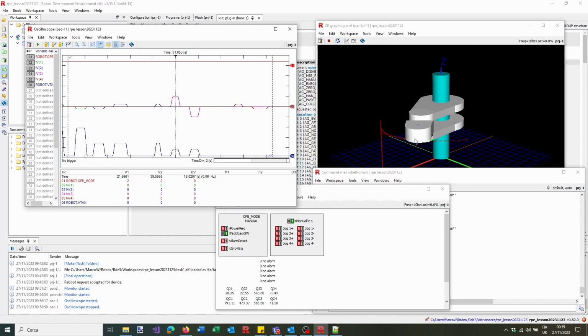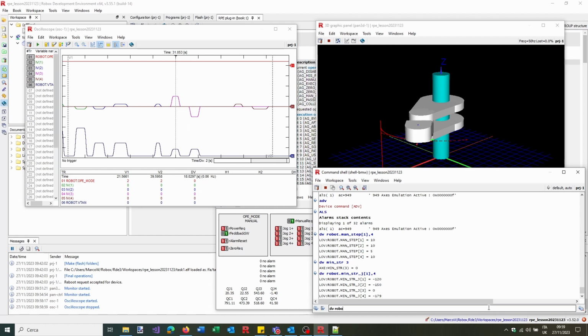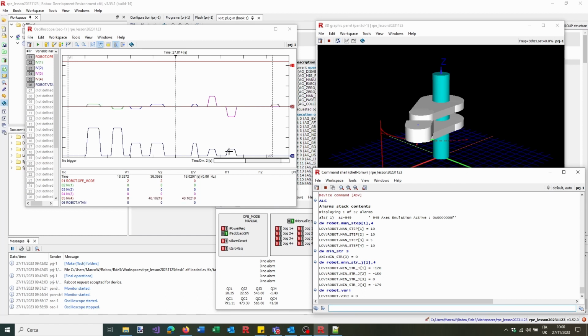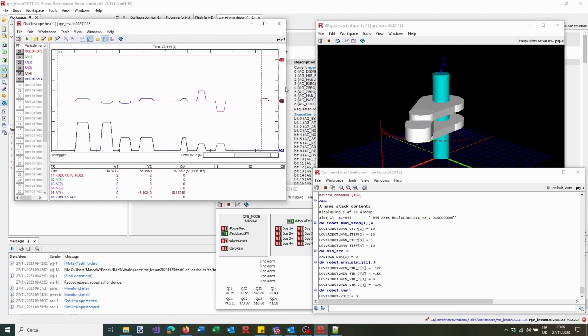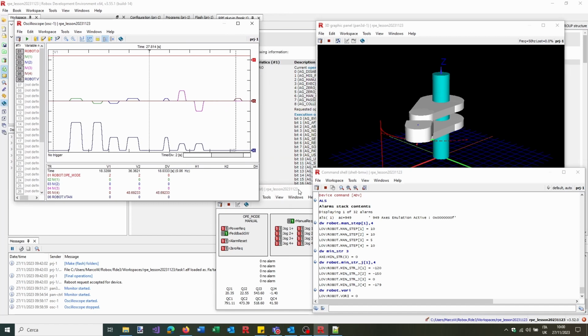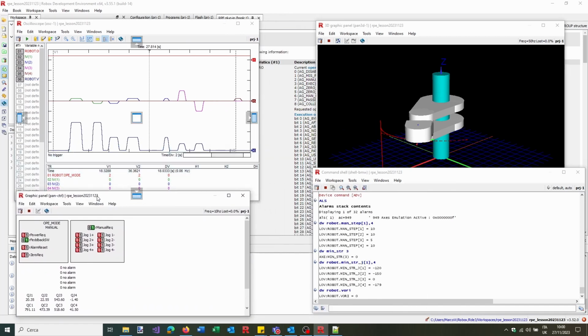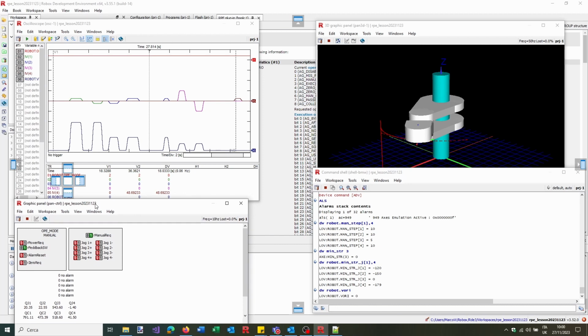It is only changing the orientation. So if you want to see it together with VTAN, you can also have V-ori like this. So this is the speed of the orientation path. Normally we check VTAN, which is the limiting one during all the motion. Normally the orientations are just following, and so we don't care too much. Now okay, we can see that we are doing all of this kind of motion.